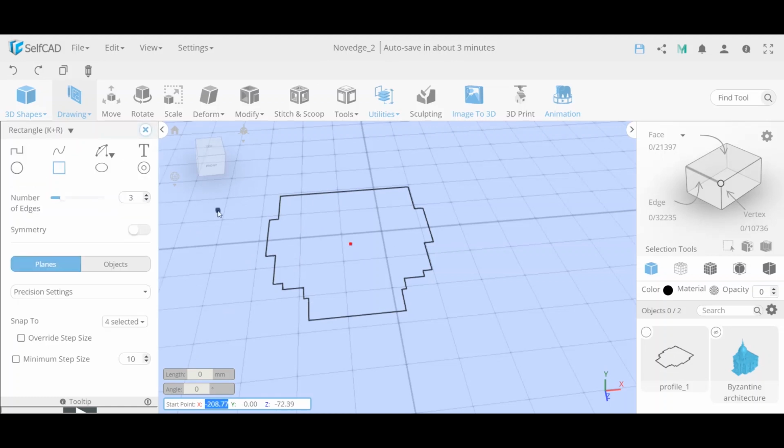The other way, the way I would like to do it, is to use, you see I have turned on over here snap to all profiles. So even though this is not selected and is a different profile, we'll still snap to this. So I can start snapping from this profile to this profile and make this wrap out over here. You see I'm making the first rectangle, and then I can start building out other rectangles over here and cut out the pieces.